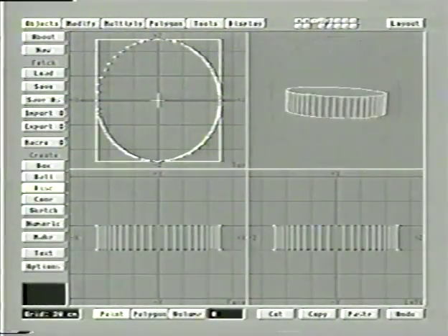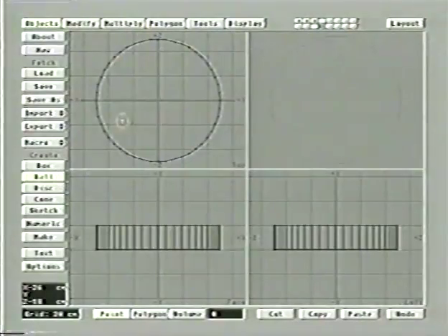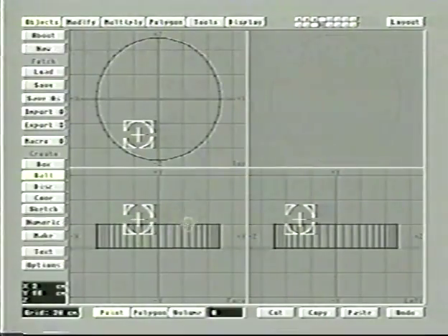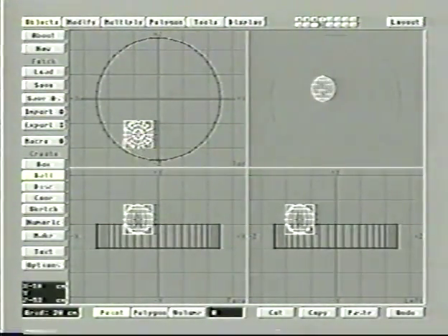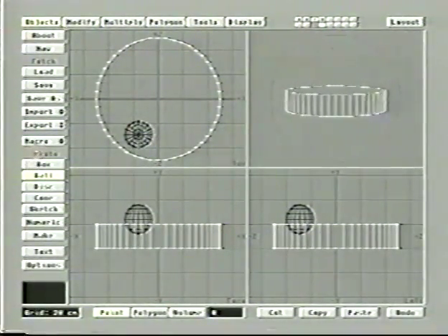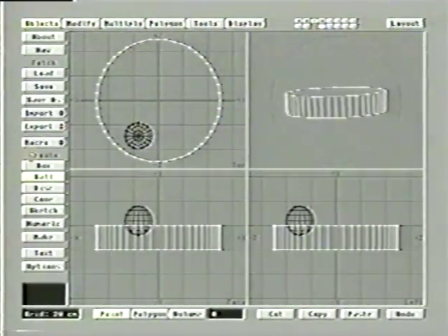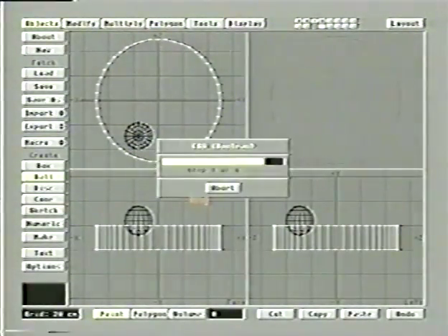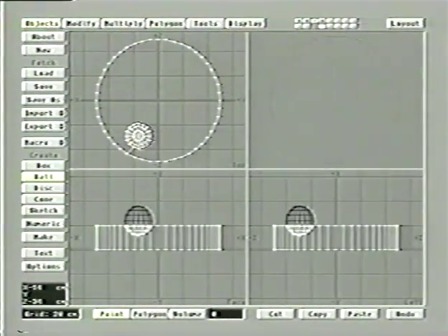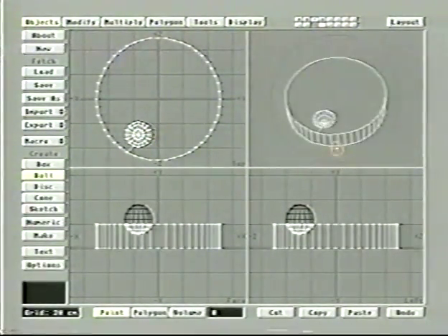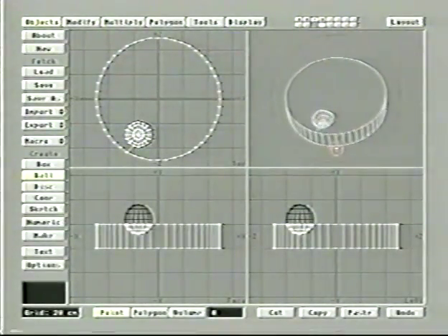Here's the wheel itself. Go to another layer, make the wheel visible in the background. And now I'm going to drag a sphere that goes part way in, but not all the way in. I just want to be able to take a chunk out of it. And since the sphere only goes part way into the disk, we switch our layers, that quote key again. You can see how the quote key itself can save 3 years of your life. So let's just do a Boolean, Shift B, subtract, and it's going to subtract the inactive layer from the active one, which will cut a chunk. Again, you'll still see the sphere, but it's not really there. It's just in the inactive layer. You'll see what it did was it took a nice chunk out of the wheel there. So you don't have to go entirely through the object. You can just go part way through.